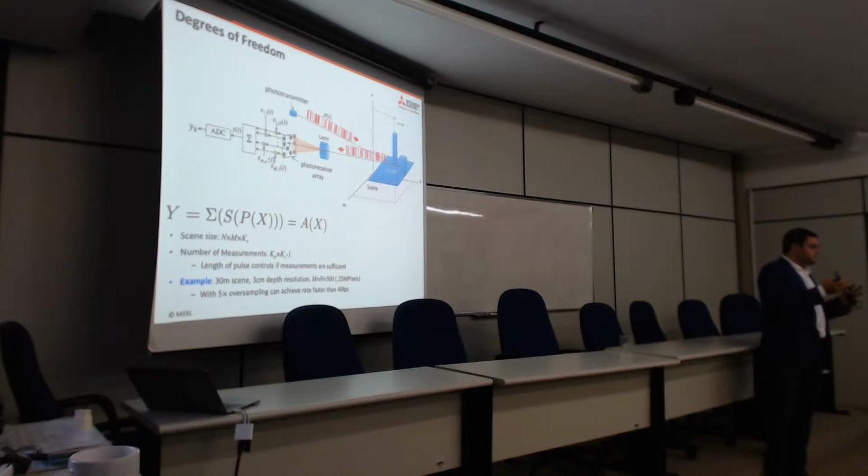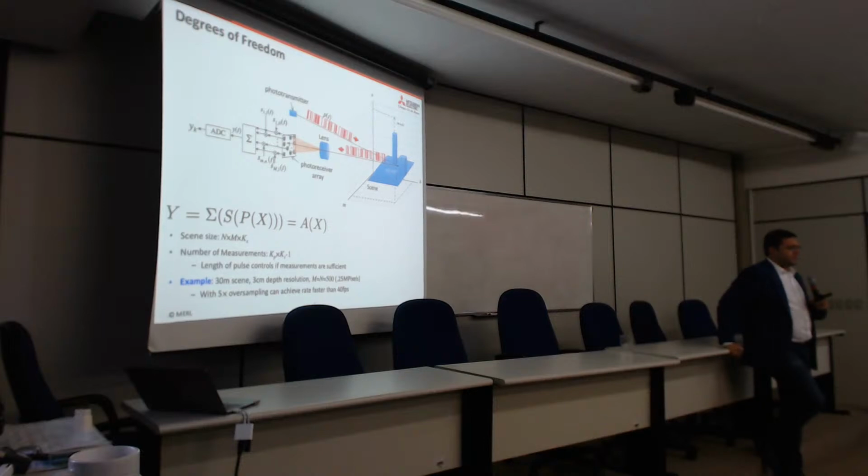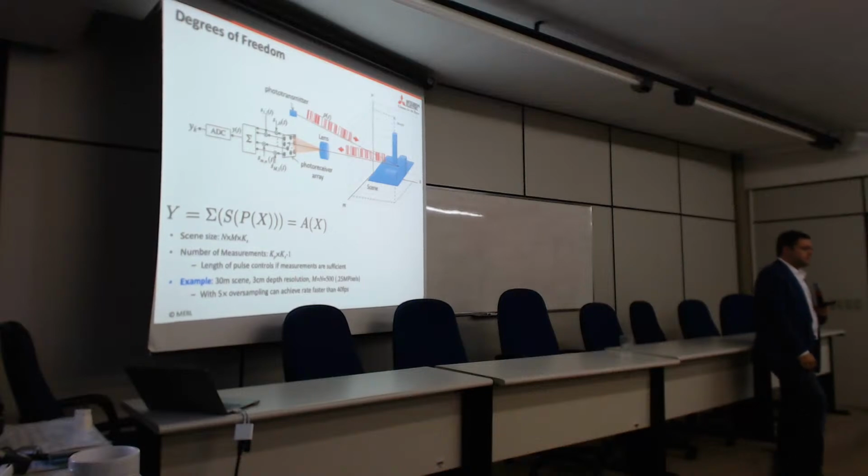That's also easy. Your problem is the A to D converter, because you also need your A to D converter to run at that frequency. But again, if you go down to 1 bit, that's still just a comparator. And you have comparators that run at 60 gigahertz. I mean, I can show you the spec.